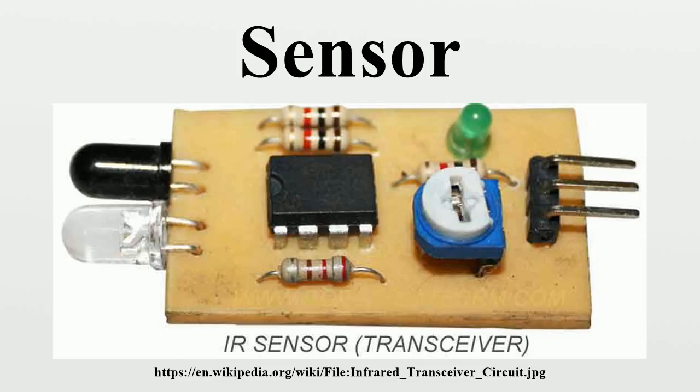A sensor's sensitivity indicates how much the sensor's output changes when the input quantity being measured changes. For instance, if the mercury in a thermometer moves 1 centimeter when the temperature changes by 1 degree Celsius, the sensitivity is 1 centimeter per degree C.